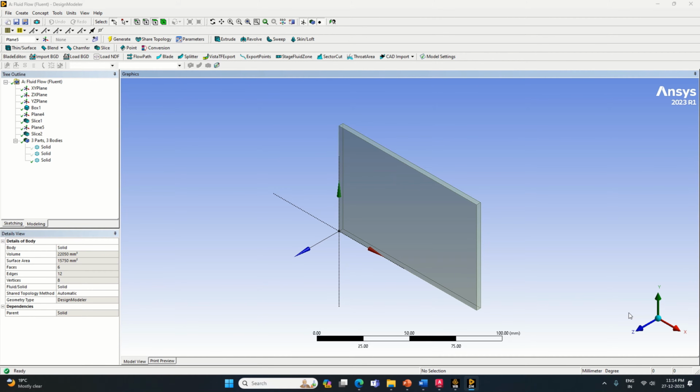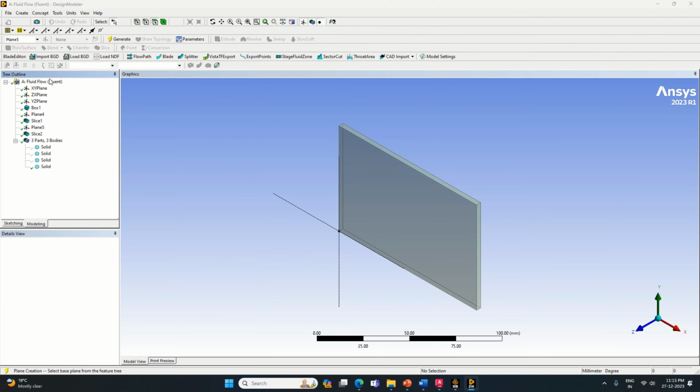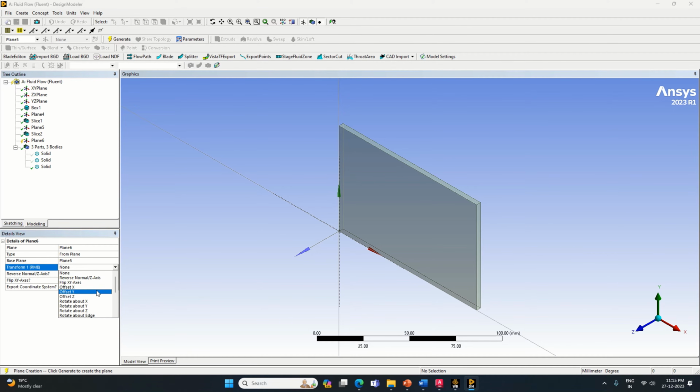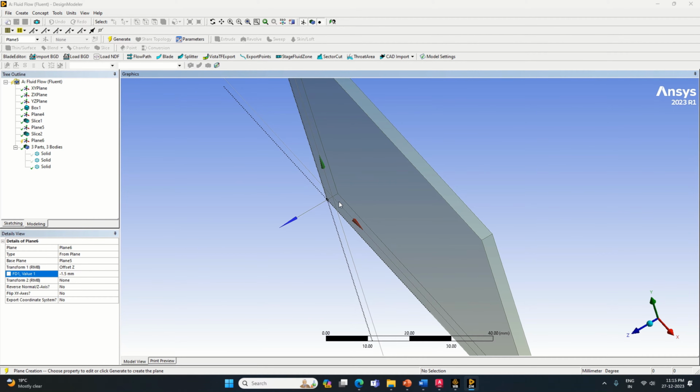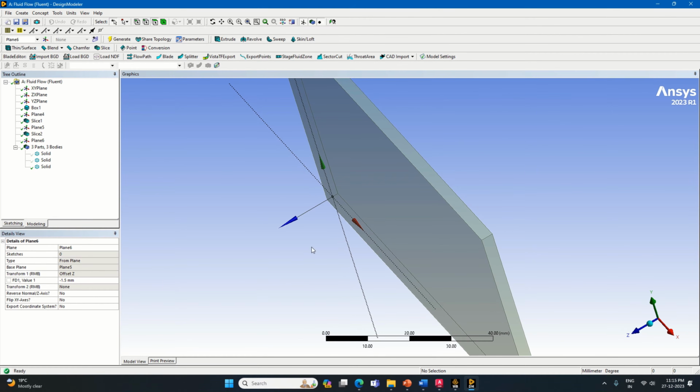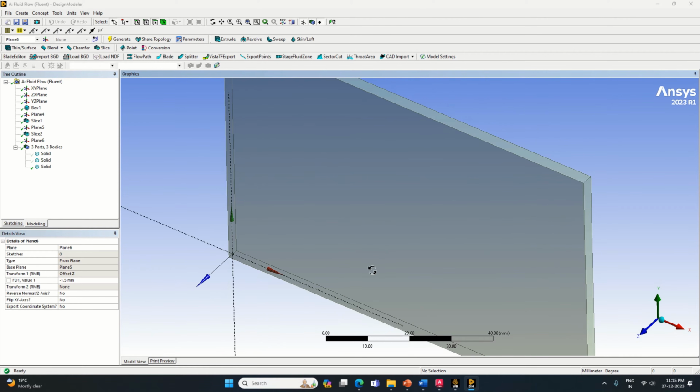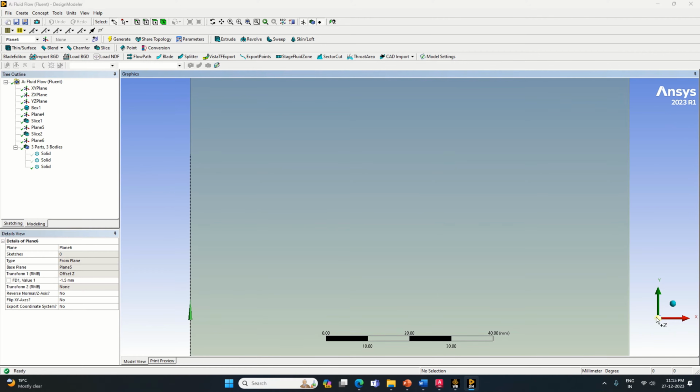So this is 3 mm, so we'll create one more plane which is at 1.5 from this. So let's say offset, plane 5, you can offset it again by Z. So I'll put it minus 1.5 here, so it will go inside of this, so we'll get somewhere at the center. So make it here, so we'll have one more plane which is generated exactly on the inside.